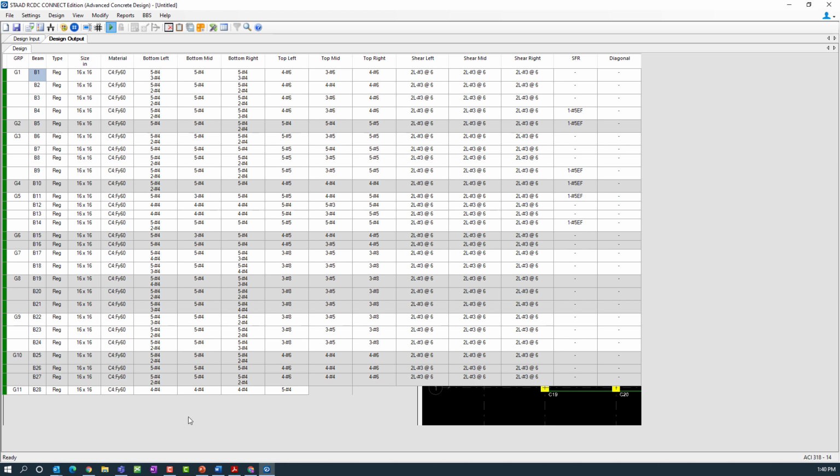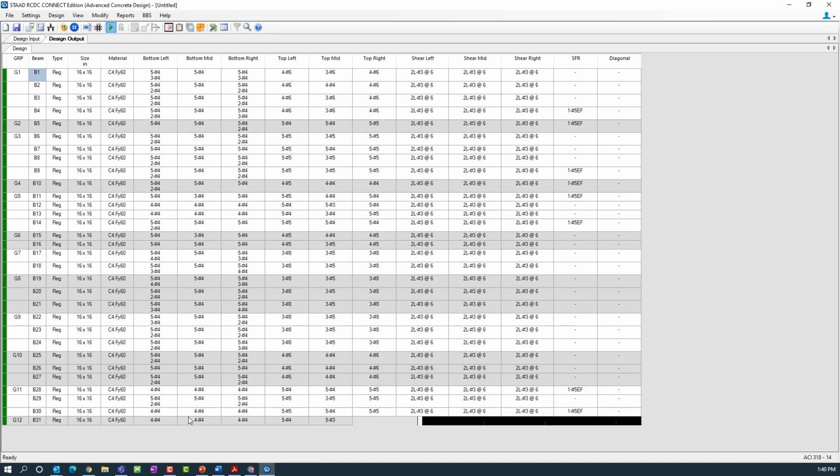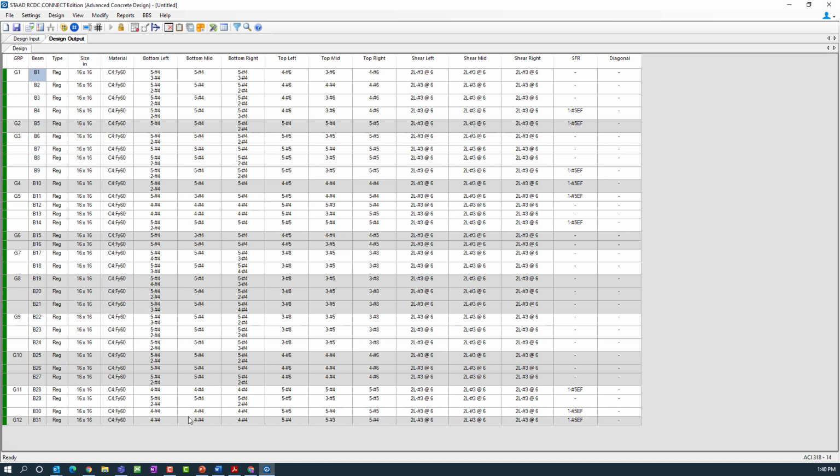Now, in this preliminary design, I did already do a little bit of grouping. If you notice, when I imported my model, I grouped across levels, which basically means that a beam on level 1, 2, and 3, since those are the levels I selected, will have the same reinforcement. Now, the forces in those 3 different beams will always be considered in your design. But no other grouping was considered. Continuous beams were considered. No other grouping in plan was considered.